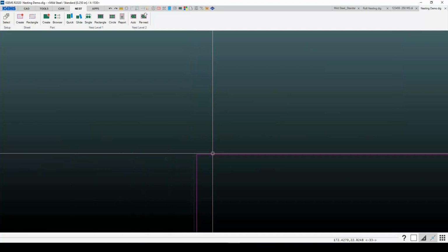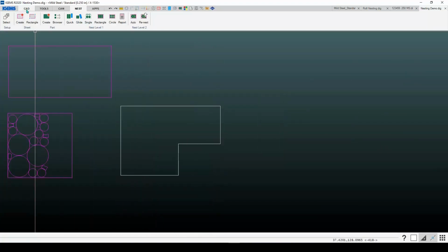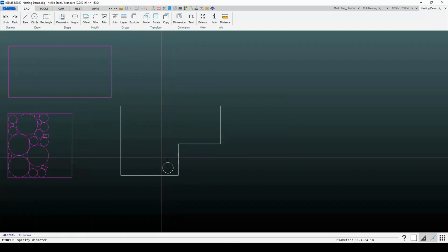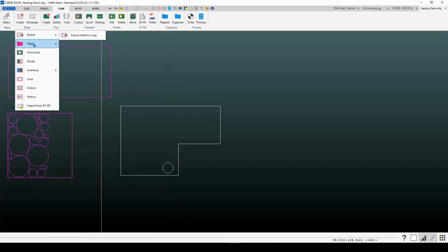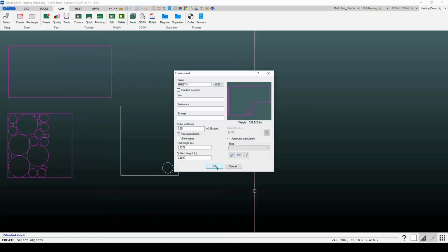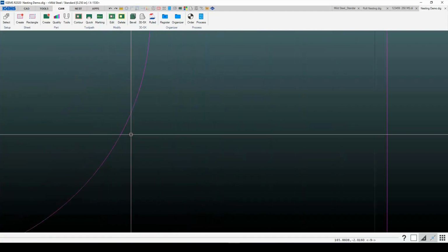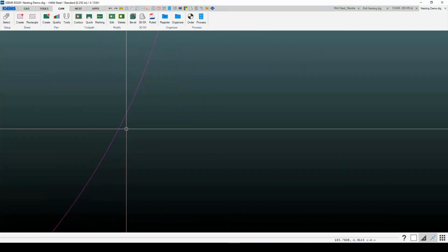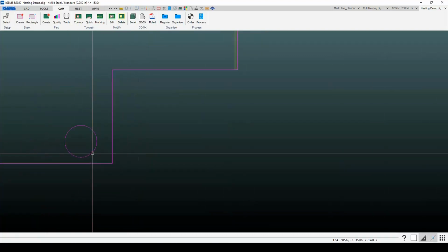And we've got our web around there. Let me just back up one step. One other thing you can do is draw in other geometries. If you've cut something out of here already, you can draw that in. Just note that when you create the sheet out of something like this, it will put that 1/4 inch collar width around the outside, but there is no collar width around this portion here. So if you're going to draw something like I've done here, you want to make it a little bit bigger so that it doesn't nest parts too close to that void in the sheet there.